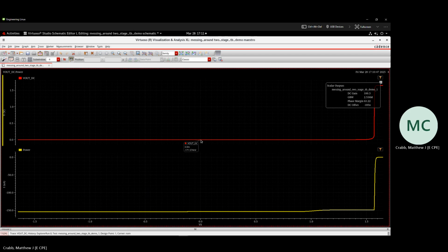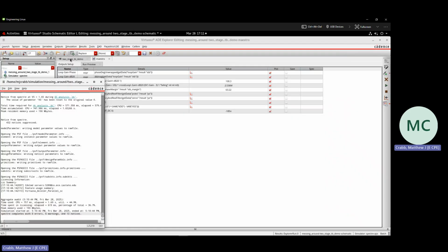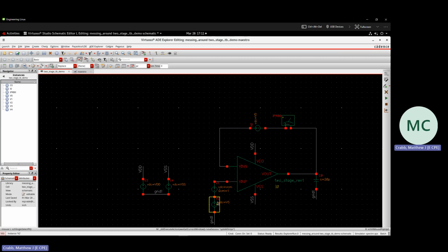And so because, go back to the schematic, we have it set up so that this node is set to VS. And then there's a VS drop from this node to this node. So if our op amp has very high gain and it's operating, then it'll force these inputs to be equal. So this will be VS, this will be VS, and then we'll have a drop of VS to here. So output will be 0 volts. If our op amp's gain drops off, then our things will fall apart and our output might not be forced to 0 anymore.